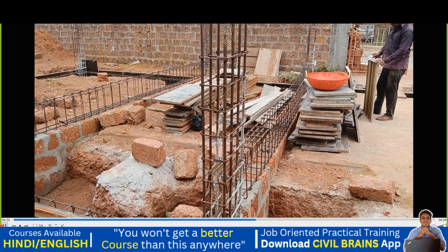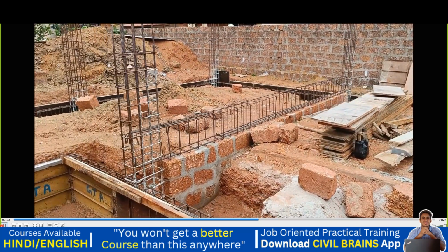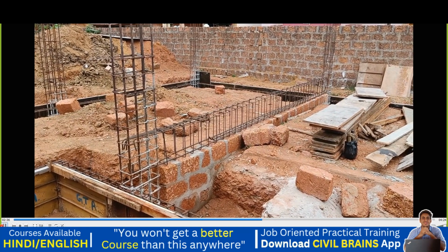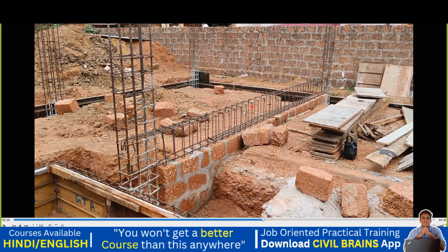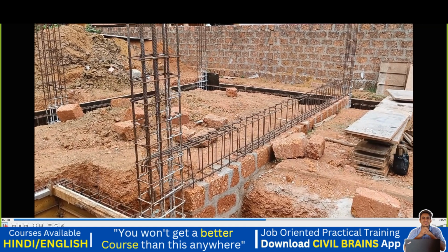The same concept has been adopted, and for the same building I'm showing you the structural drawings. Again you can see it here also. See here: top steel, bottom steel, then the bottom curtailment. This is the left extra, this is the right extra. So again this is how the reinforcement is given. You can see the top left extra, bottom curtailment, and top right extra. So again I'll play the video here.